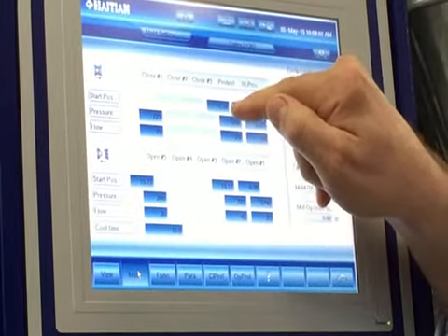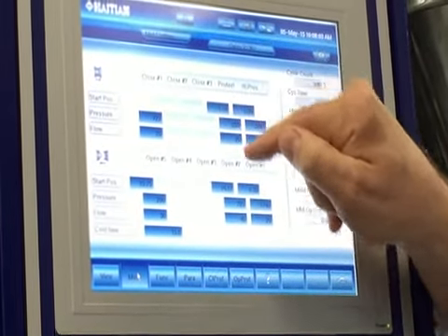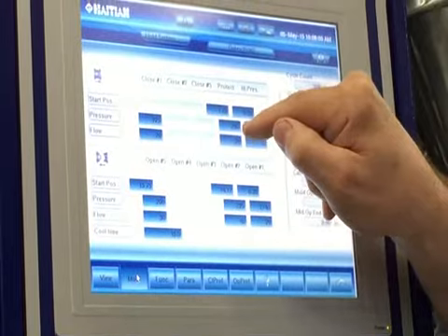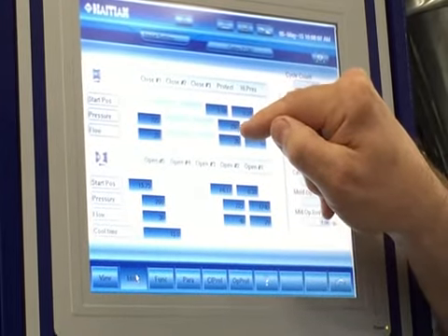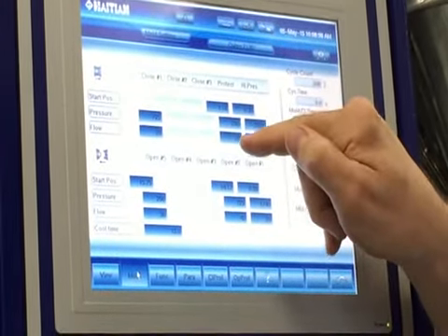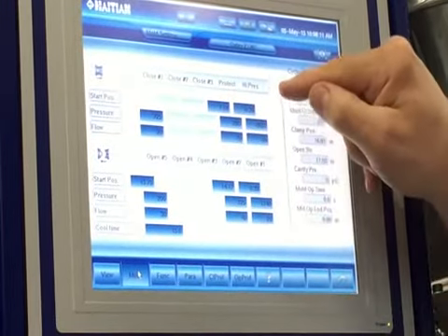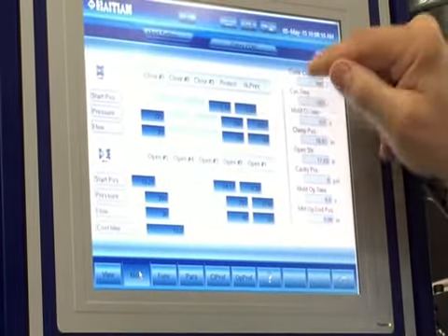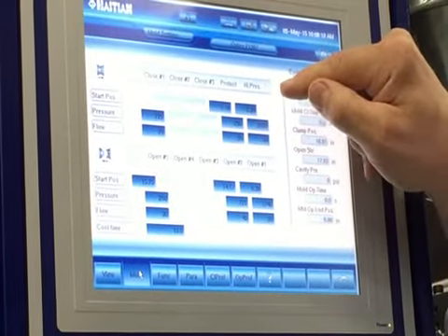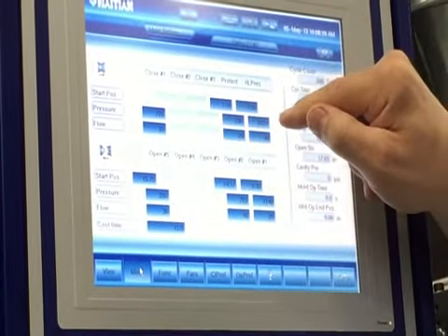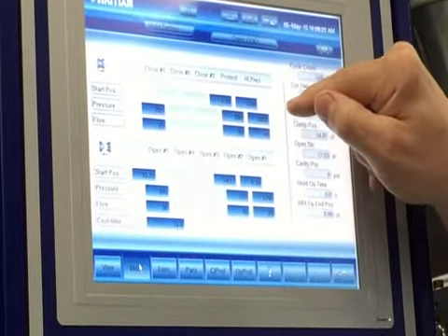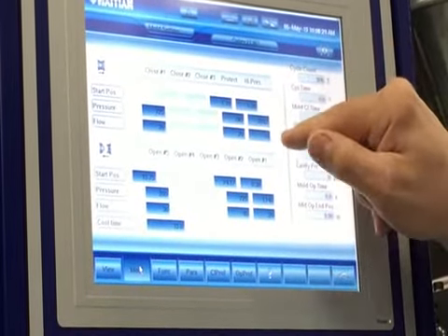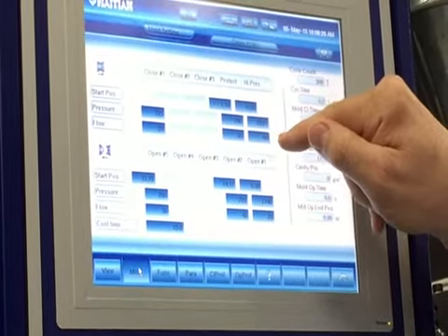When we get to the 1.18 setting, we are going to drop down to 290 psi for pressure and 20% flow. Once we get to 0.39, we are going to go into the high pressure, which is lockup, at 2031 psi, which is maximum system pressure, and then 44% flow.